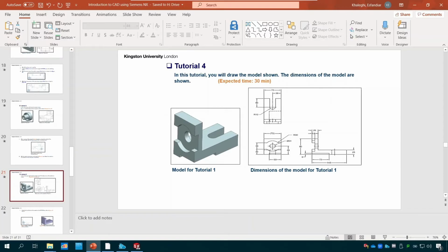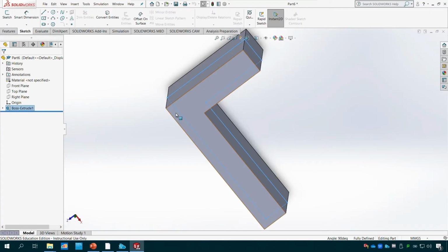So what I'm gonna do, I'm gonna click on sketch, pick this one up first, then click on sketch, and what it does, it actually converts that one as my reference plane this time. So let me put it to normal too, and I'm gonna make a normal rectangle. From here I'm gonna make that rectangle, and I need to apply the dimensions.